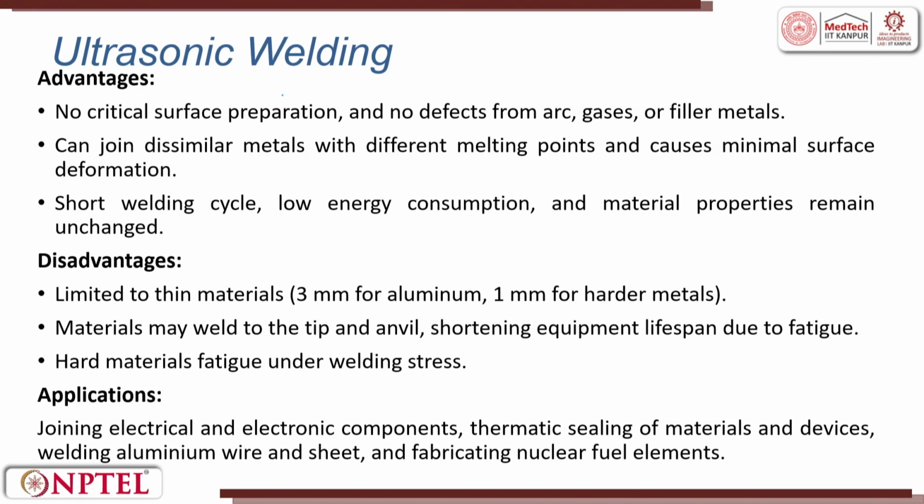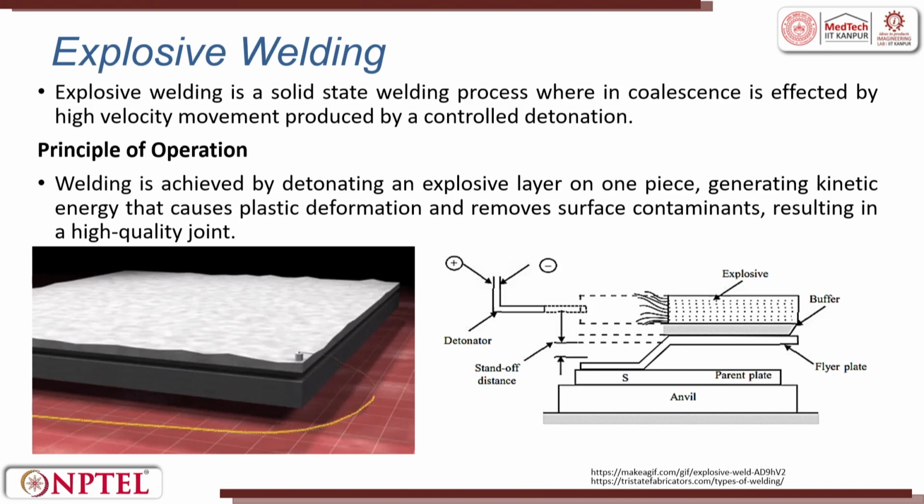So, the advantages are no critical surface preparation is required, joining of dissimilar materials is possible, short weld cycles, and low power consumption. Joining of electrical and electronic components, hermetic sealing of materials and devices, welding aluminum wire and sheet, and fabrication of nuclear fuel elements can happen under the ultrasonic welding process.